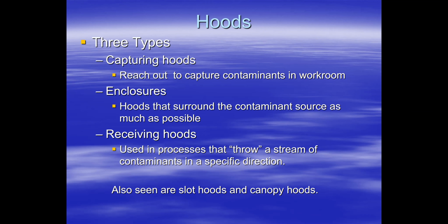Another type of capture hood would be a canopy hood, a kind of capture receiving hood that you might put over a vat where the process is hot, so it's natural for the materials to rise. You're receiving them because you're placing it there, but you're capturing at the same time.